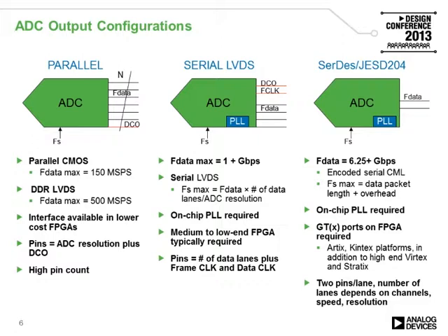Low voltage differential signaling uses a pair of complementary outputs, thus twice the pin count for the same number of bits as in CMOS. But with the double data rate interface typically used, the number of traces, pins, is on par with CMOS implementations. Parallel interfaces are high pin count, typically converter resolution plus clocks and some framing signals. But the interfaces are available in the lowest cost FPGAs.